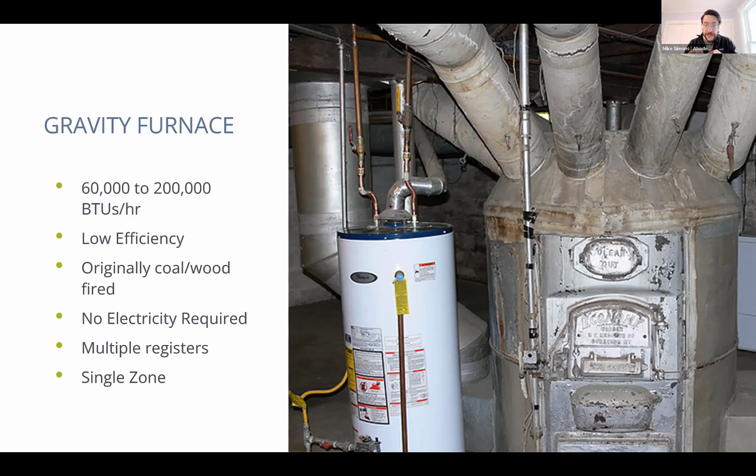And over here, you would just have this long, continuous simmering wood fire or coal fire. In the morning, someone would be shoveling coal or wood into the unit, and then it's just this long continuous burn, and that worked perfectly fine with natural convection. Once people switched over to home heating oil or natural gas or these extremely energy rich fuels, there was so much heat extracted in the combustion process that it was just instantly 500 degrees and then off. And that didn't work well with this type of distribution system.